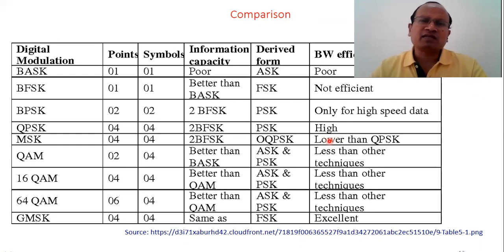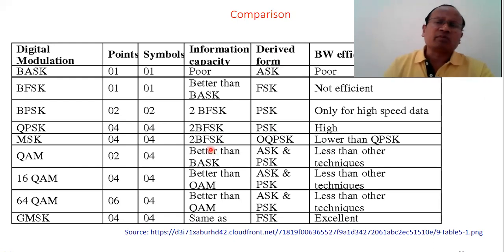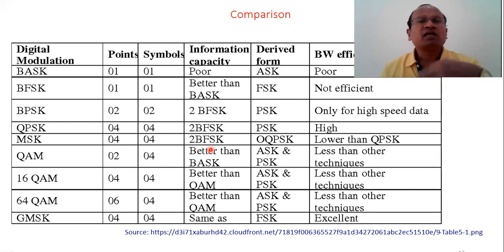So in analog modulation, there are popular methods called amplitude, frequency, and phase modulation. Similarly, there are 3 broad categories called ASK, FSK, and PSK, in which there will definitely be a change of amplitude, frequency, and phase in the carrier signal, and that change will depend on the instantaneous value of the modulating signal. But the major difference between analog modulation and digital modulation is that in analog modulation, the instantaneous value of the modulating signal changes in a continuous manner. So the change in amplitude, frequency, and phase is also continuous.